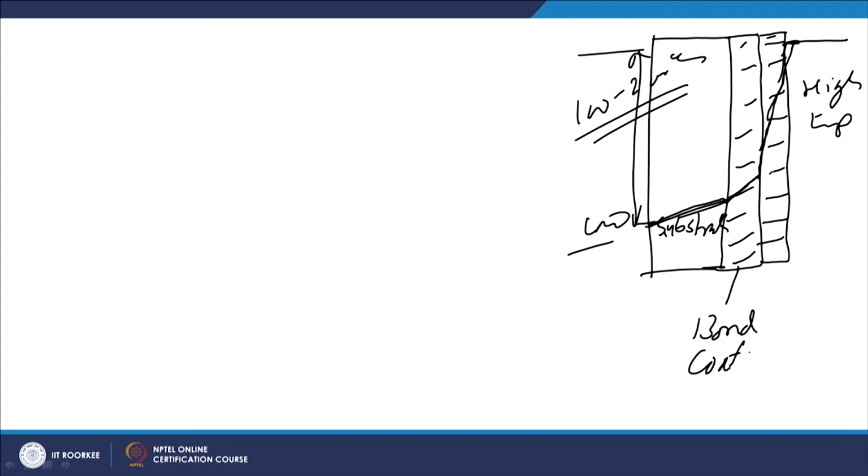So, maximum drop is offered by the TBC material, then a little bit of help is also given by the bond coat, and then there will be a temperature gradient across the substrate as well. This reduction in temperature is favorable with regard to the kind of degradation which will be controlled in the substrate material, which in turn will help in improving the mechanical performance of the component being exposed to high temperature.